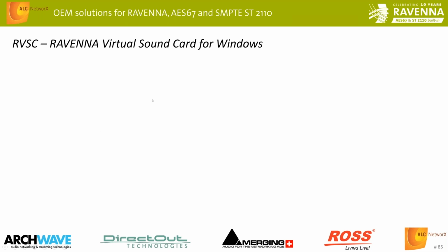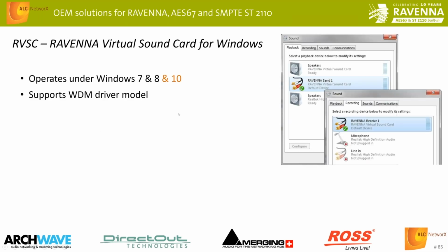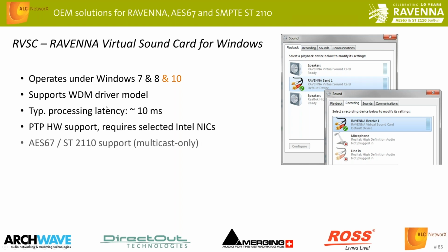So then I already mentioned the Ravenna virtual sound card. Basically, it operates under Windows 7, 8, or 10. Although with 10, we have seen some limitations most recently, which can be circumvented, but 10 gives us some headaches. But as of now, we can still solve those. It only supports WDM driver models, so no ASIO support. The typical processing latency is about 10 milliseconds.